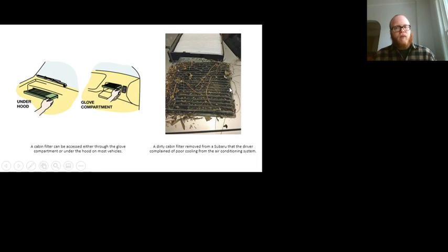You have to be careful with air filters like this, because when you pull them out, it's sitting right above the blower motor, so any debris that doesn't come out with the filter could fall down into the blower motor. If that happens, I've had good luck with just turning the blower motor on with the air filter removed and all the stuff out of the way. It tends to cough the stuff out. Otherwise, you'll hear it in there flapping around, and a customer's going to be pretty grumpy about that.